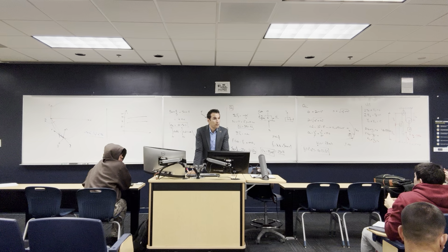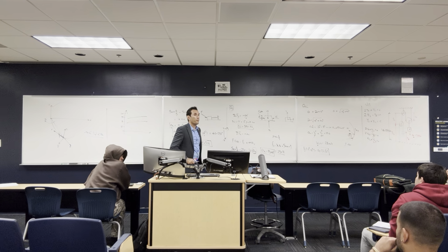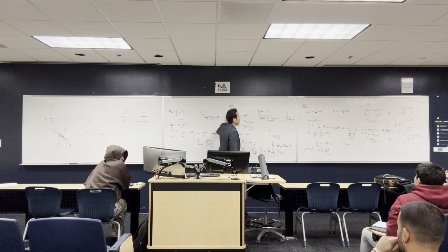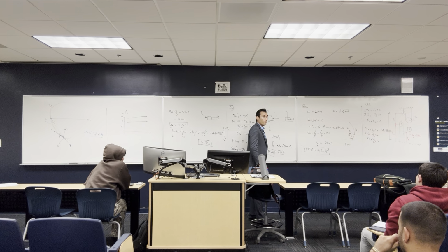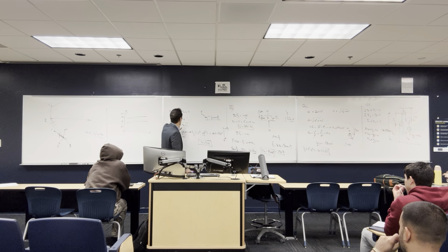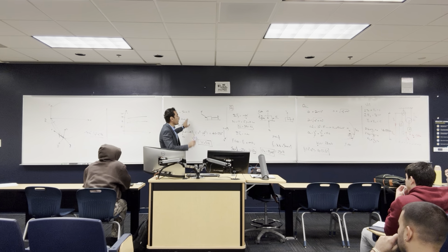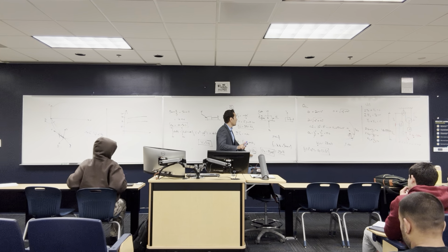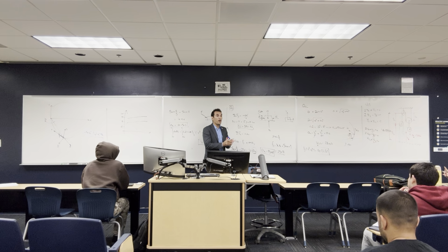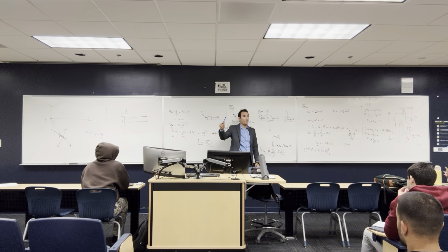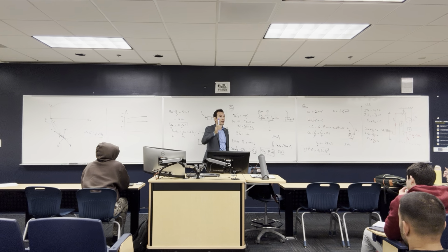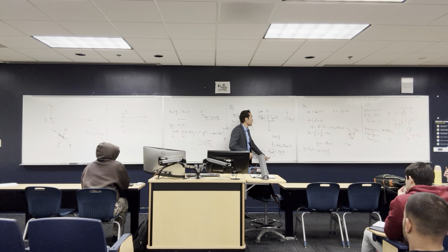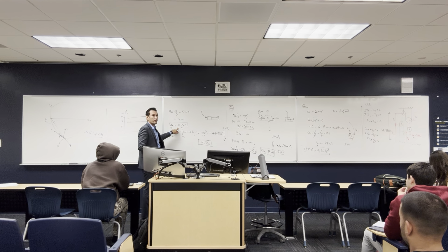For question 3, when you found AX equals 15 meters per second squared, when you plug that in over there, could you explain again why you knew to? Oh, okay. So when I did this, it was just to get AX at a specific point, at S equals 0.5, but A is changing. A is not constant. AX is not 15 meters per second squared for all the movement. It starts with a number at 0.1, 0.2, and keeps changing. So the change with S was this equation.